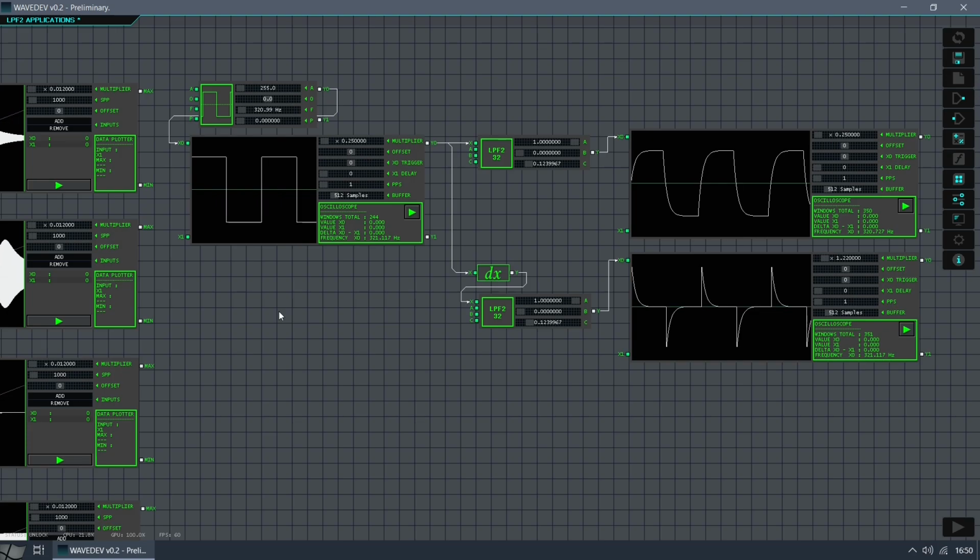But this equivalence is only valid under isolated conditions. In the digital realm, signals are not energy limited, and do not face impedance problems. Multiple digital filters, either connected in series or parallel, can work independently of each other, but not their passive counterparts. Just keep in mind that a strict circuit simulation using these filters can give slightly different results. But that can be made up later.